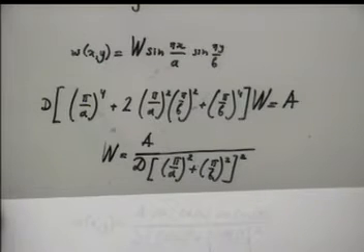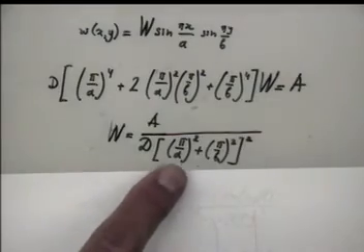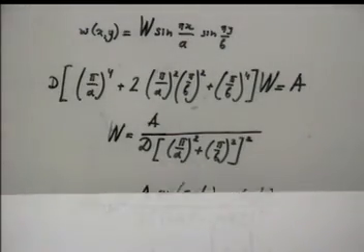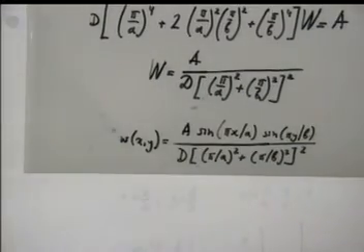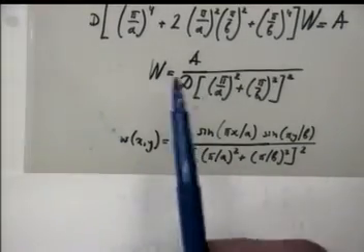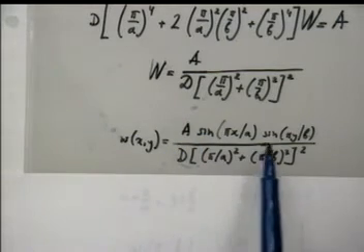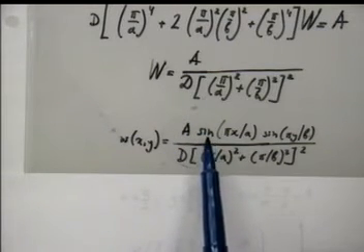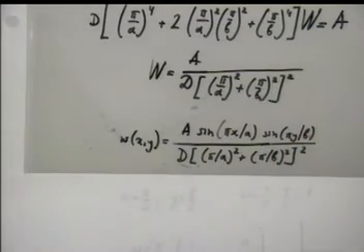So from here, W equals this, a over d times pi over a squared plus pi over b squared. Now I substitute. I found capital W, which is this, divided by this. Now I have to multiply by the function sine pi x over a, sine pi y over b. So that is w. You see, in this particular case, we solved the problem immediately.